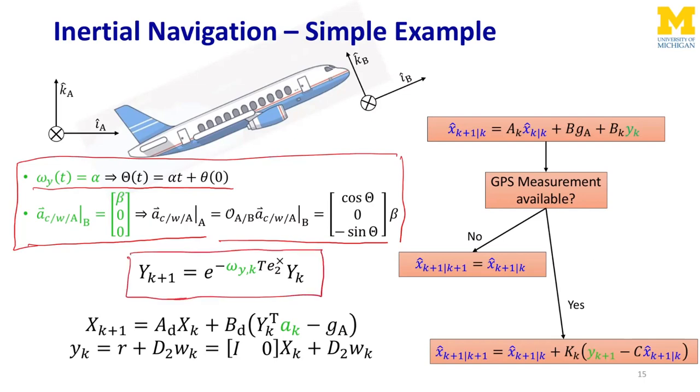We do not have any measurement of the attitude, so there is no output to merge, but we have some estimate of the positions available using the GPS, which can be merged with the dynamics model of the state, position, and the velocity. So big X is the position and the velocity, and now our measurement is going to be the position given by GPS, and that position ends up being this component of this state.